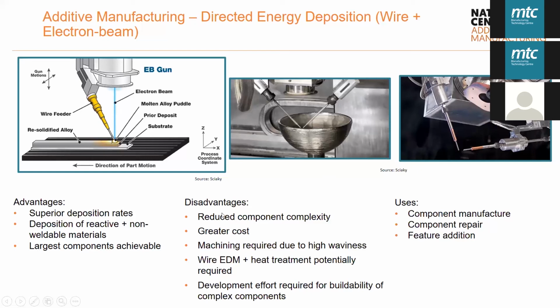Main drawbacks and disadvantages are greater cost. You have to conduct everything within a vacuum, so the cell itself needs to be evacuated, which can incur quite a substantial amount of cost every time you process. But most of the other disadvantages mirror all the other DED systems, where you'll most likely need to wire EDM, plus development cost and effort for building complex components, and reduced complexity in some cases.